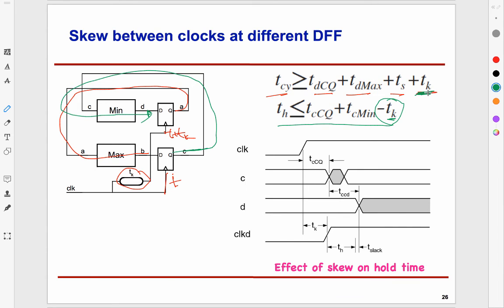Now, when you design the chip, depending upon how the wires get laid down on silicon, things may go either way. So you would be conservative and think of the skew as something you are taking out of the budget. But by cleverly playing with it, you could also use it to your benefit. Not a great design strategy, but nevertheless one could do that.